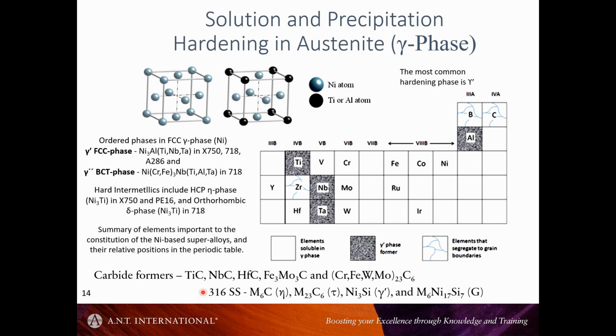So typically one adds, or the suppliers of different materials might add, other elements, titanium, niobium. I'm not sure they add hafnium, but there's an interesting story about hafnium I'll tell you later. And these are all carbide formers, and they will compete with chrome and either minimize the amount of chrome that's depleted or completely eliminate any of the chrome depletion, simply because they preferentially then soak up all of the carbon.